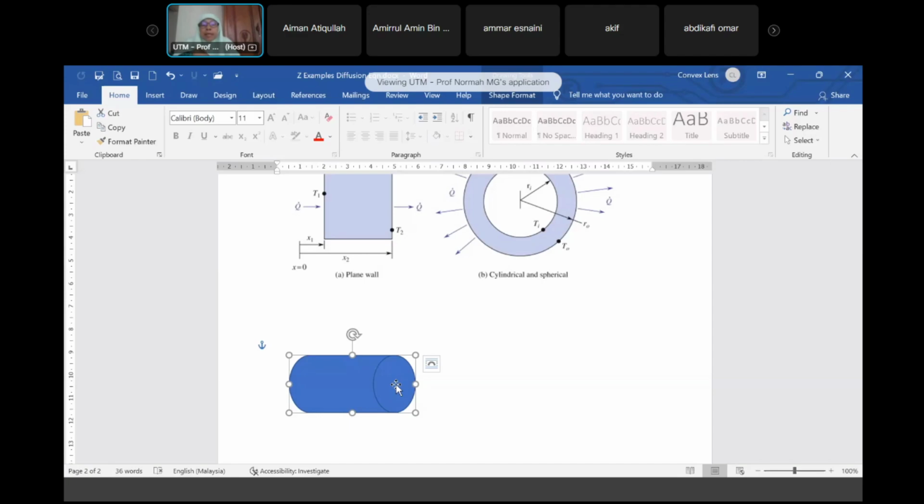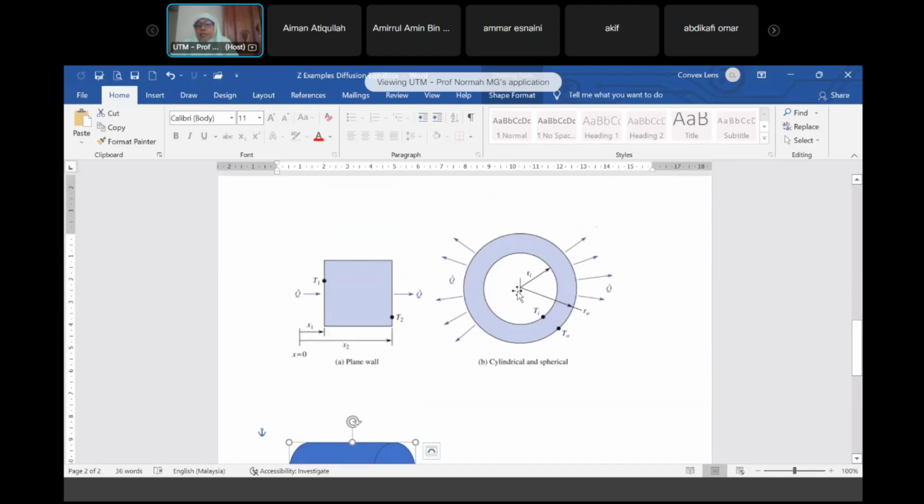For a hollow cylinder, dT/dr is not 0 in the middle because you may have something there. You may have steam, chilled water, etc. So your boundary condition would have been at R1, temperature is given or heat flux is given, and at R2, R outside, temperature is given or heat flux is given, or maybe you have a convective boundary condition.